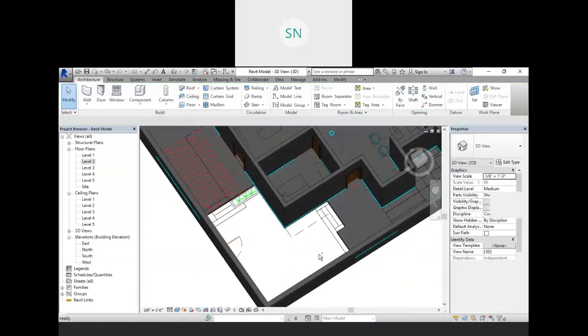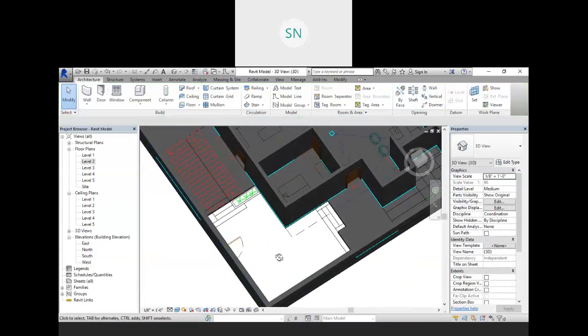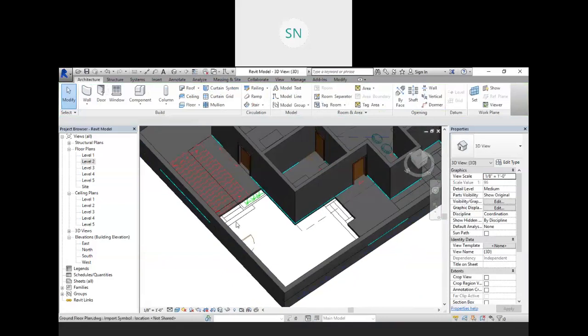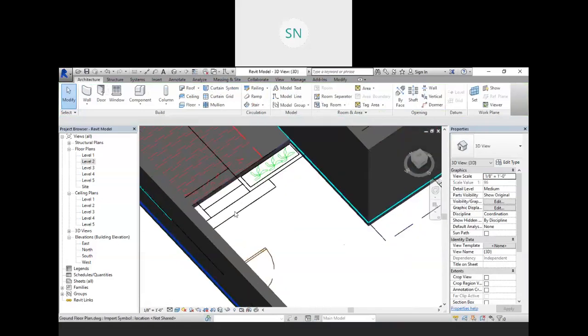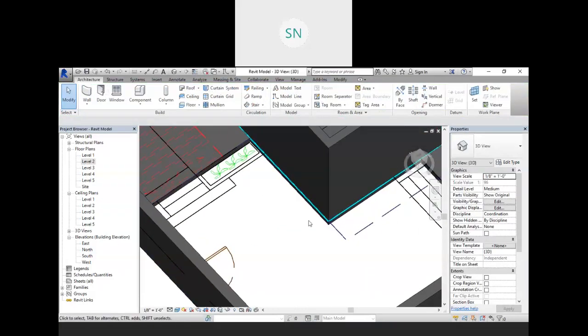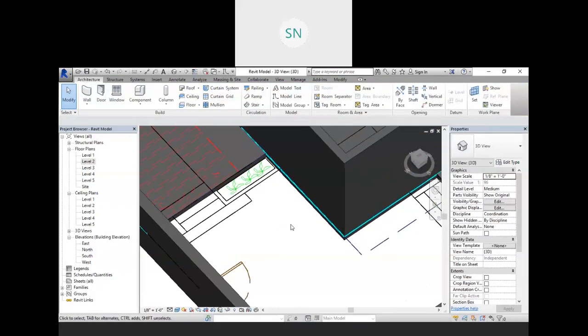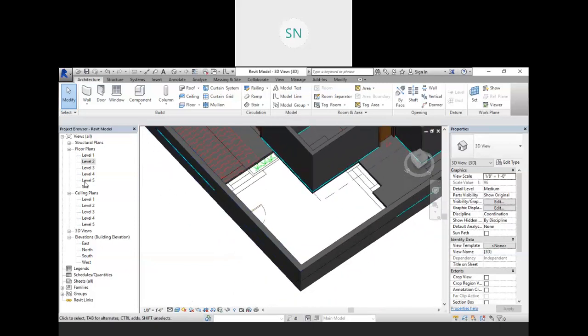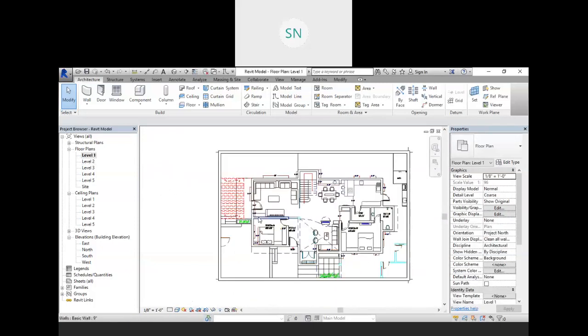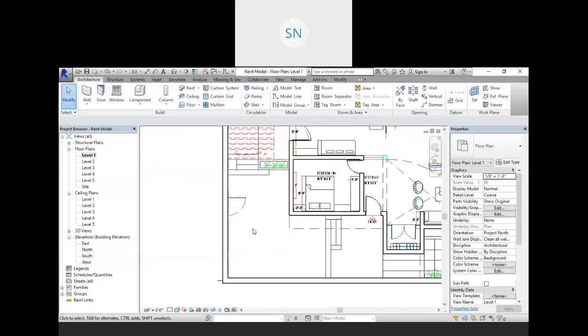Now we have to create something over here. For the bottom, let me create one tiny floor. Then when we learn about the extrusion and parametric modeling tool, you will get the idea how to create these steps, right? So first go to level 1 and here we want one more floor.